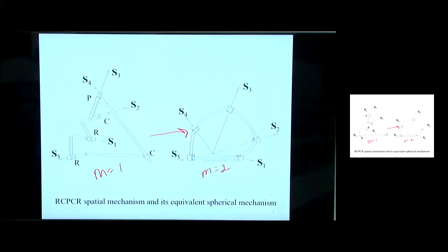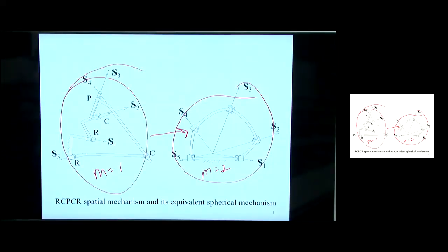Because when you analyze the spherical mechanism over here, because it's 2 degrees of freedom, when we go into our toolbox, the best I can do is to find 1 equation and 2 unknowns. So the problem's not going to decouple. That means I need to get a second equation in those 2 unknowns, and I'm going to have to get that equation from the 3D mechanism. Now those equations are going to have joint offsets, the S's, and link lengths, the A's.